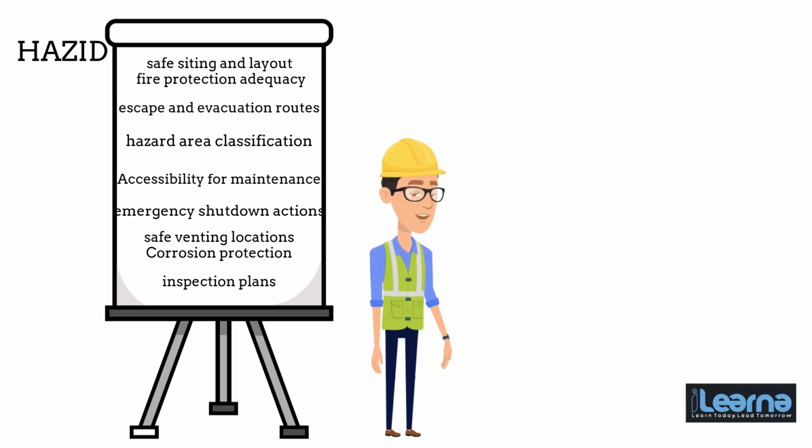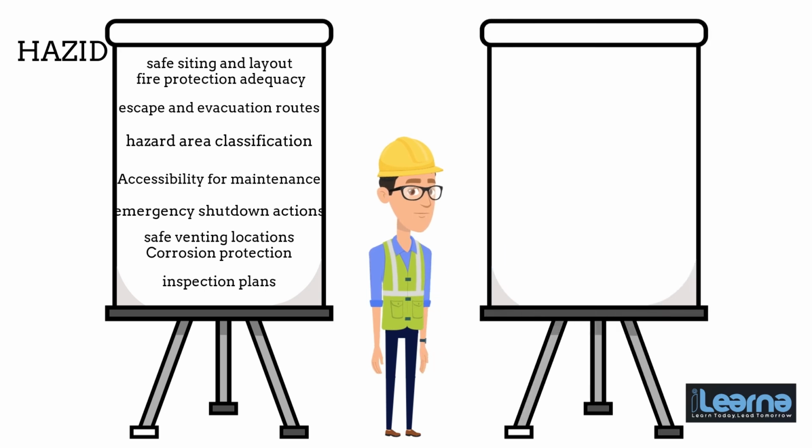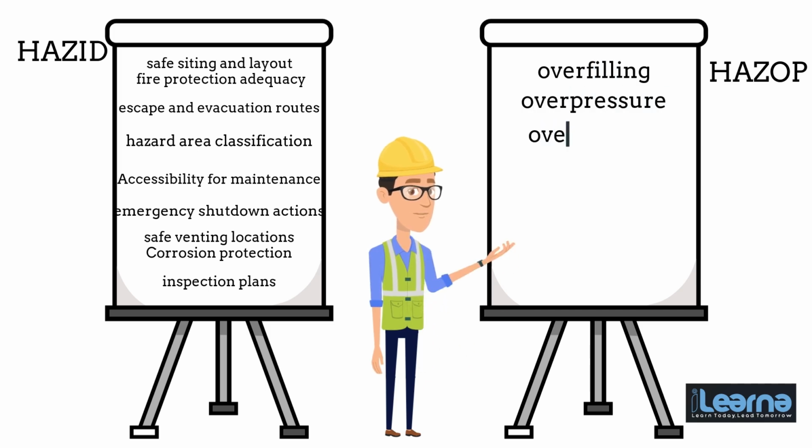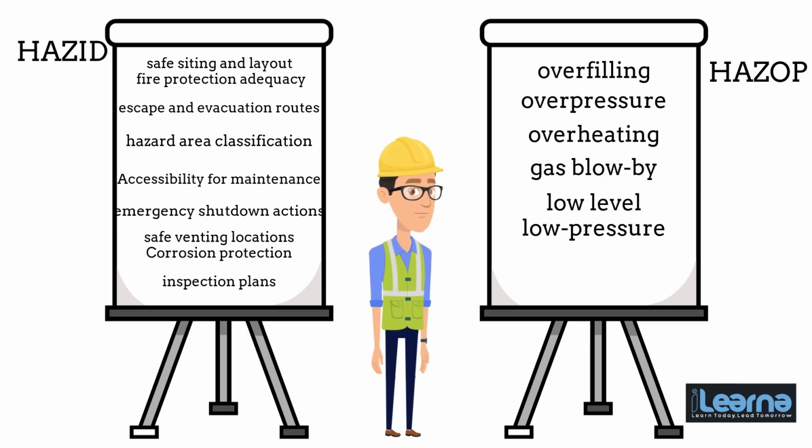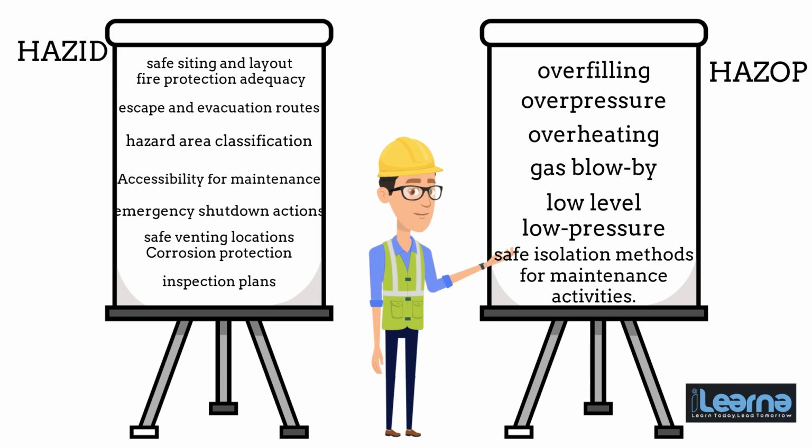For HAZOP, the focus shifts to more process-specific concerns, such as overfilling, overpressure, overheating, gas blow-by, low-level, and low-pressure scenarios. It also covers safe isolation methods for maintenance activities.